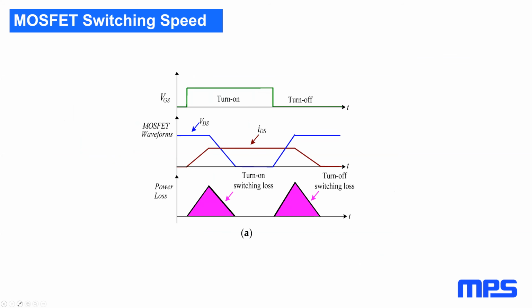So I've shown you how the gate drive current, or the resistance in series with the gate, affects the switching time. But why do you care? A couple of reasons. Obviously, you need to switch fast enough to pass whatever waveform, like a PWM signal, you want to drive.